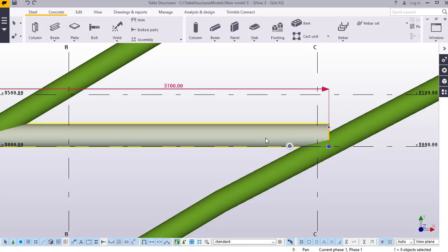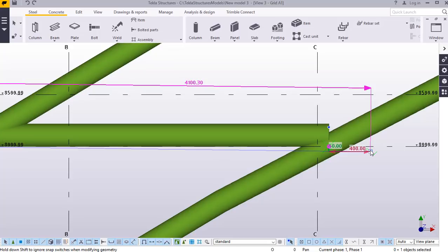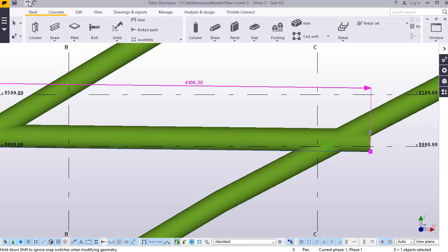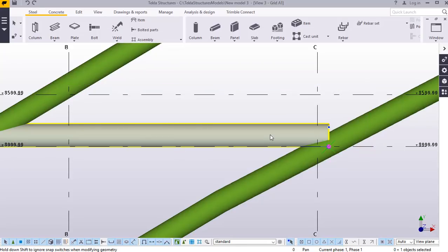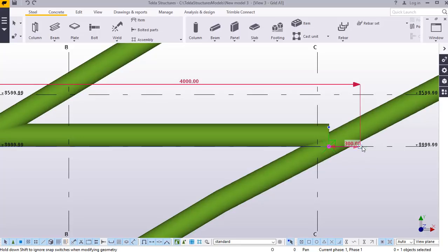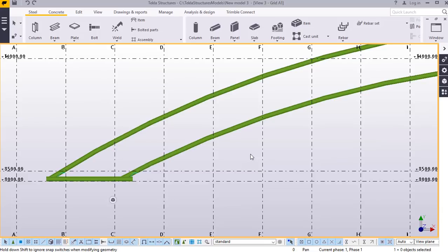After selecting this, just click on this position and press your left button on the mouse and drag it in this direction. Drag it in that direction and leave it there. Not appropriate. Double click on that. Click on this position, press your left button on the mouse, then drag it straight. Perfect. Points that will assist us in creating the internal diagonals and verticals of our curved truss.